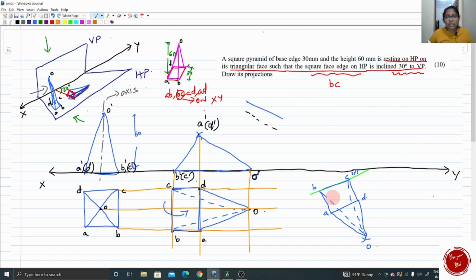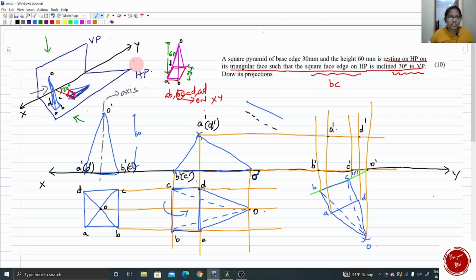Okay. Now let's draw the corresponding front view. Take vertical lines from every point and horizontal lines from the points in the previous front view. Okay, B, C and O have the lines along XY itself. Now join the intersecting points. Now how to connect these points? Start from marking the outermost points. Join the outermost points.